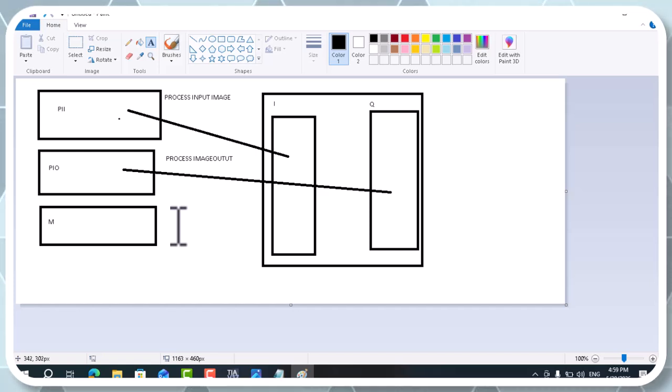And you can configure the address within M memory to retain the value of the data after the power cycle, after the power is off, or when you start the program. You can use the M memory to store, for example, data for the functional blocks.